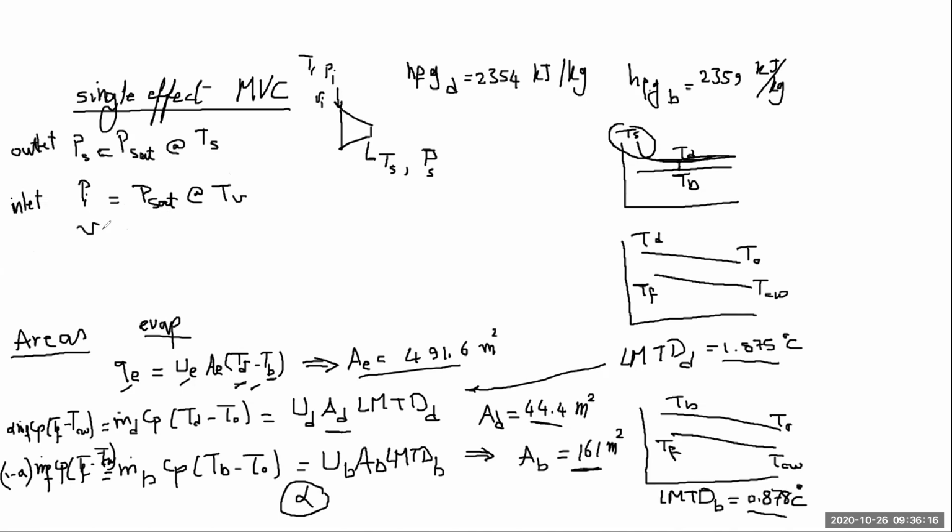And the same thing, we also need the specific volume, which is the specific volume of saturated vapor at TV. Now we can substitute in our equation here that specific work on the compressor is basically gamma, which is Cp over Cv of the vapor. That's again something that you can get from the properties, divided by efficiency of the compressor. It is given to us,